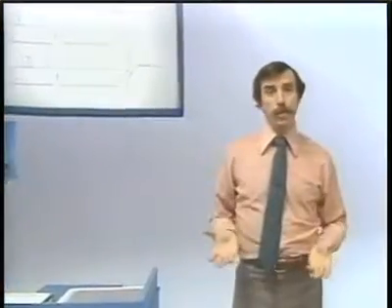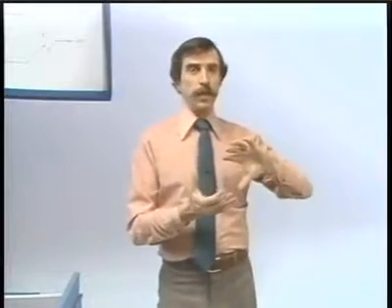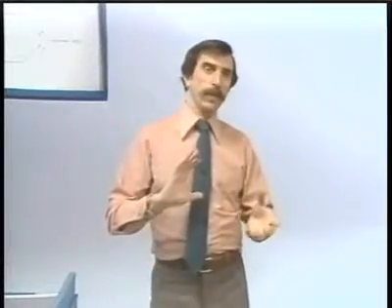So it's a very different, very important modulation scheme called time division multiplexing, in contrast to frequency division multiplexing, as we had talked about last time. I had made reference earlier to the concept of transmultiplexing, and in fact, what happens in many communication systems is that the signals are represented in discrete time. The analog or continuous time signals are represented in discrete time, and very often the conversion from frequency division multiplexing to time division multiplexing and back is done in the discrete time domain.